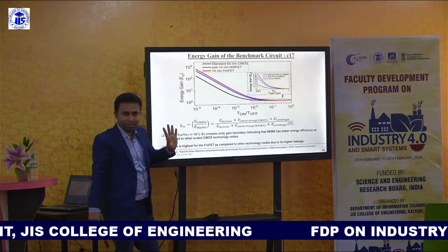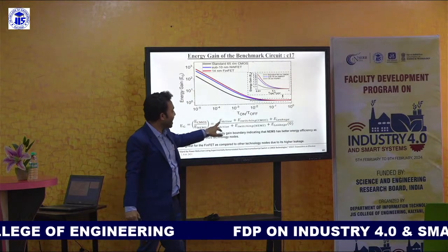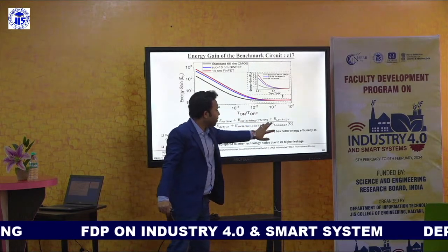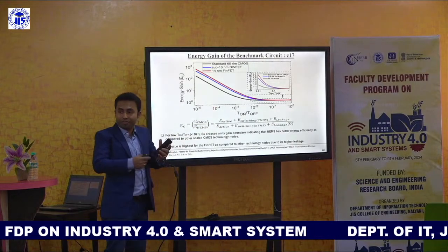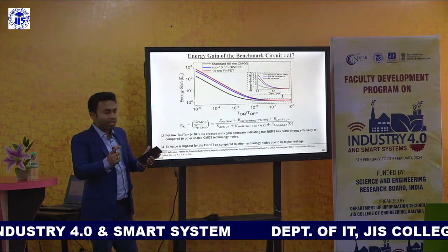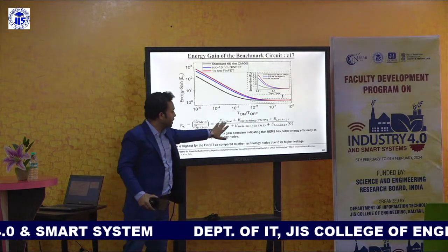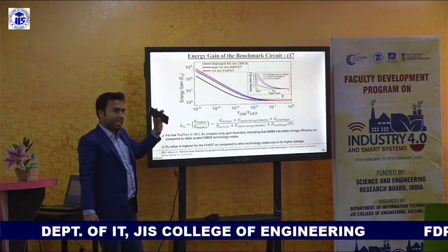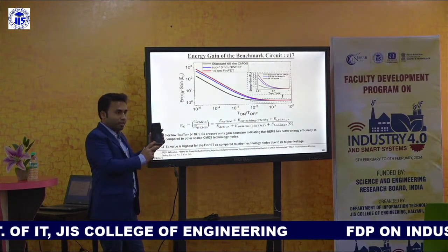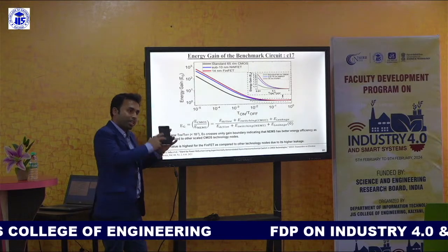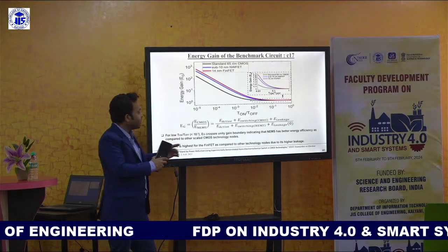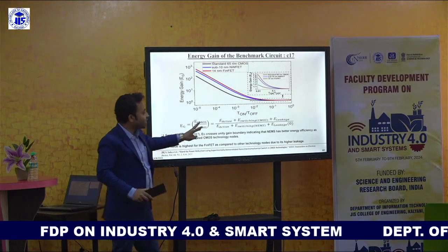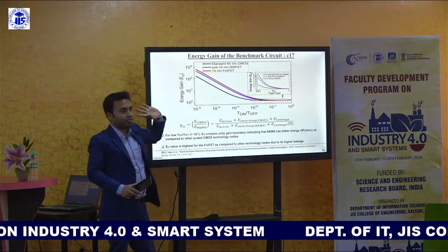The formula is basically active power plus switching power plus the off-state power. So the total power dissipation is whatever power it draws in active mode, whatever power it draws in the off state, and whenever it is switching from off to on. Those are the three powers every circuit goes through.